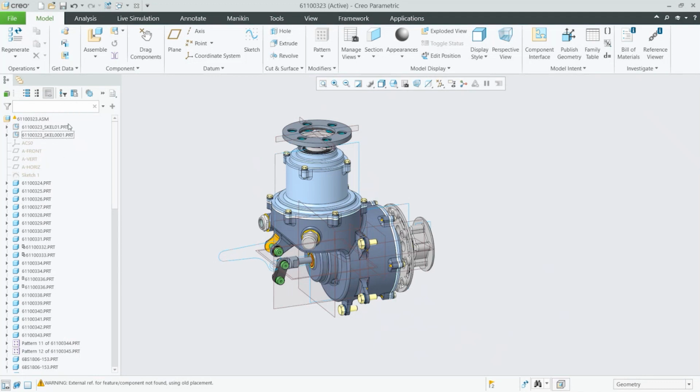So for us, usually they will have an underscore, a scan, to identify this as a skeleton model. But Creo knows this is a skeleton model because it's a transparent icon. So the advantage of using the skeleton method in top-down design is that when you go to the drawing BOM table, you can filter out all the skeletons, meaning that you don't show the skeleton in the actual BOM table.